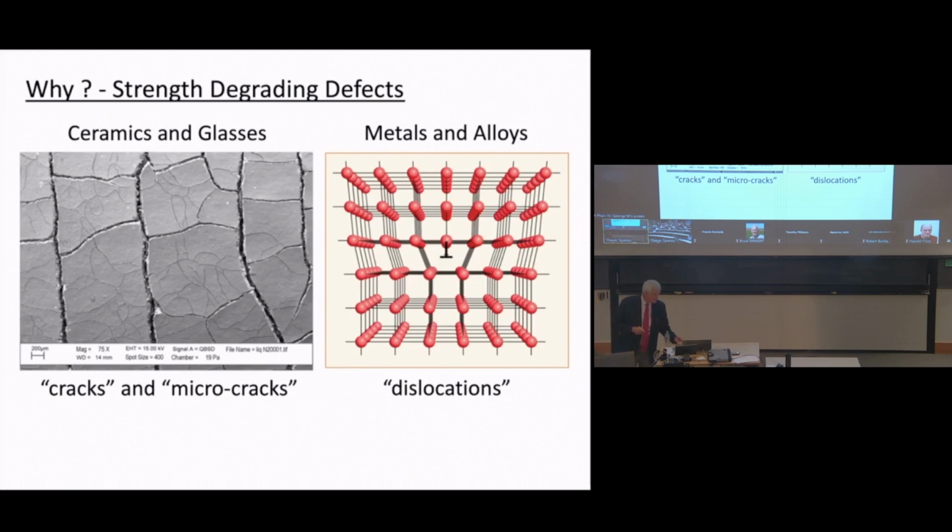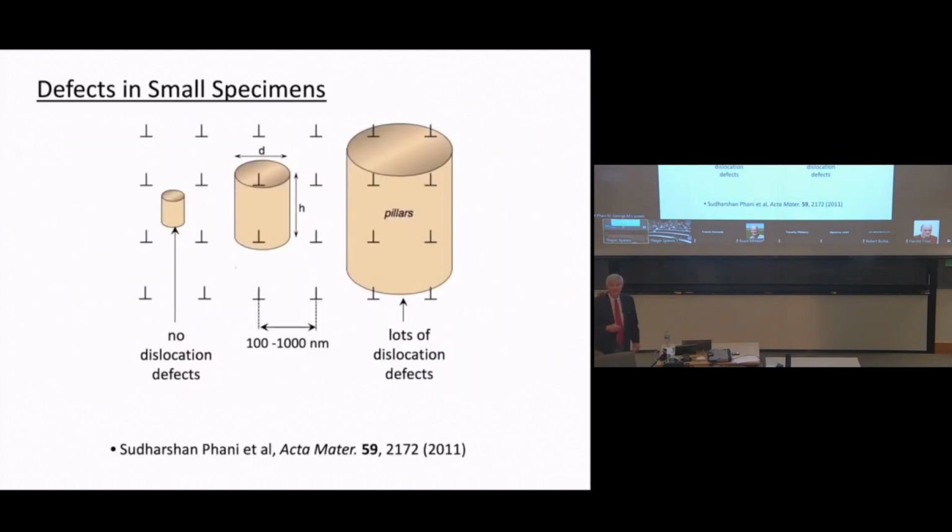Well, the way that I like to illustrate that is through this diagram, with the basic idea being this, that these dislocations are controlling the strength in some sense, okay? But there's only so many dislocations in the material. And because of that, there is a natural spacing for the dislocations, which is usually between about 100 and 1,000 nanometers, so about 1/10 of a micron to about a micron for the natural spacing of those things.